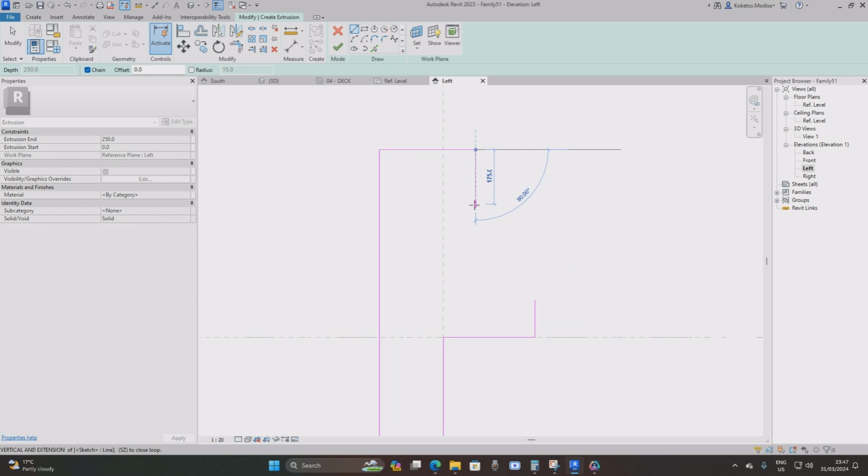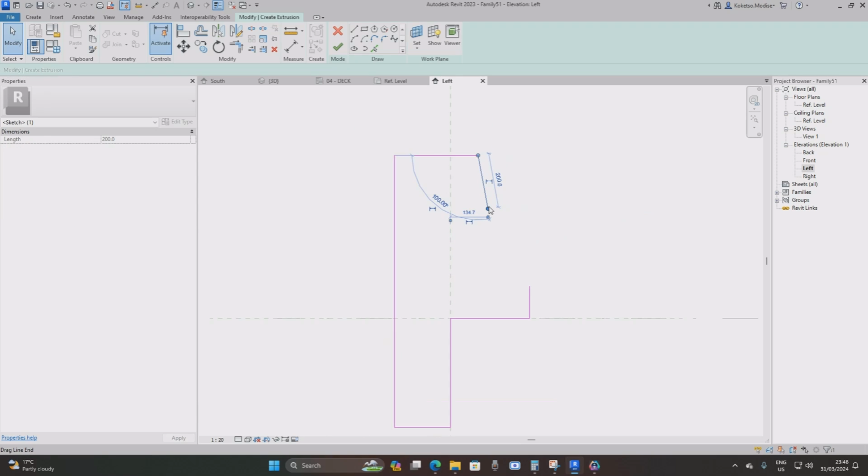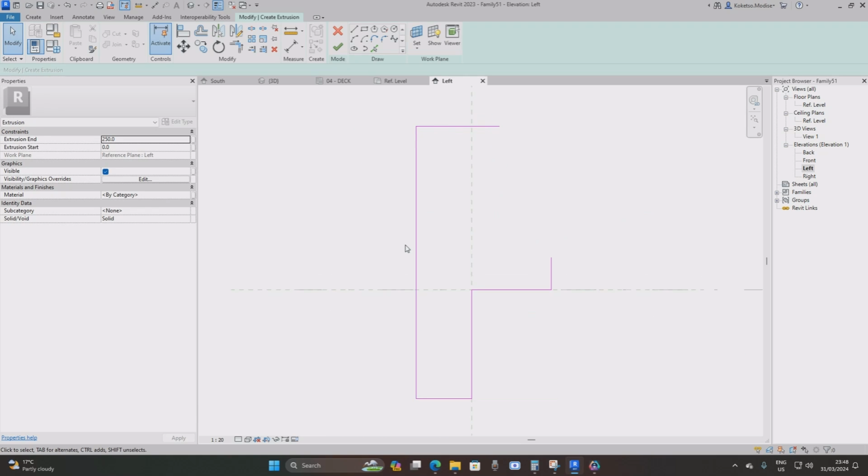from this point you're gonna take it diagonally, actually you can take it down by 200 millimeters at 80 degrees, and then you're gonna select your start and radius arc from this point to this point, and then you're gonna place it like this. So it really doesn't work, so just remove this. Let's just work on this side first.